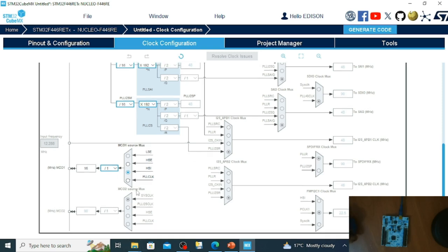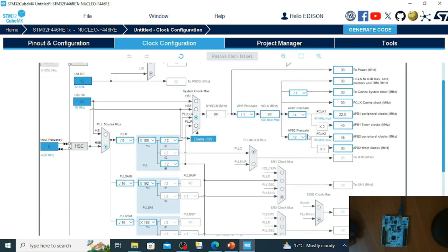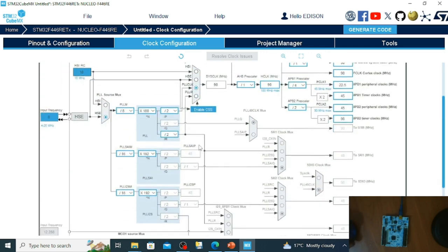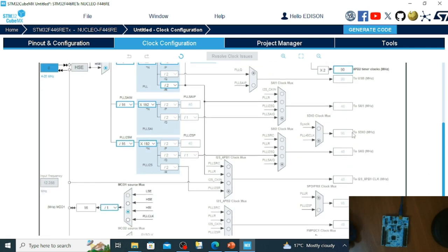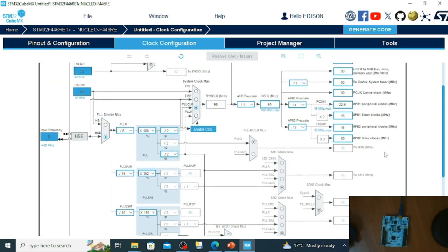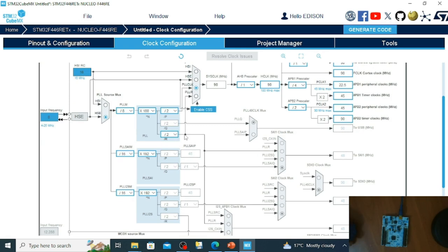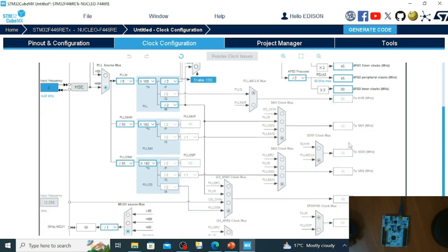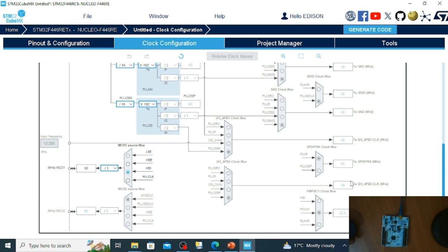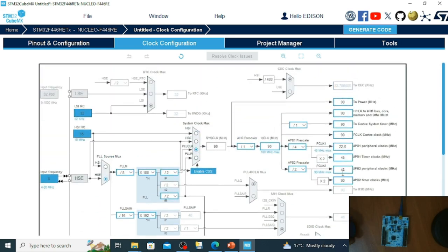And you can see that we have two, so you can choose whatever you want. Another thing to mention is that every peripheral has some frequency to run with, and you can set this by just choosing your desired frequency. It's also good to point out that before you configure peripherals, the clocks are not usually enabled so that you can save power.